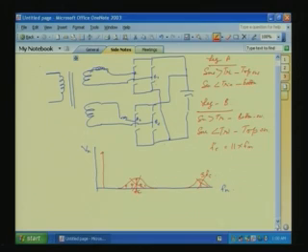Now, since these two are parallel, the triangle waveforms A1 and A2 are 90 degree phase shifted. So, all the harmonics at the sidebands of 2Fc, because of the 90 degree shift, will get cancelled here in the transformer.